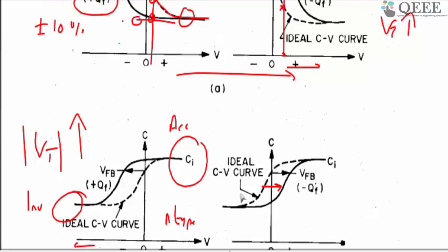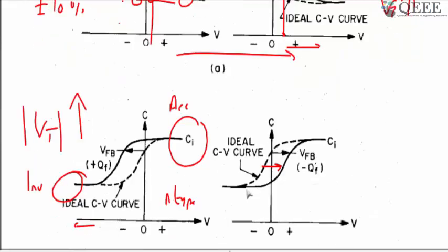So if you measure the gate capacitance, and you see it's quite different from what you have been expecting, then if you are thorough with your calculation, it shows there is some kind of non-ideality existing in the oxide. That is why this MOS capacitor is like a good process monitor. It can catch any gate oxide related issues.